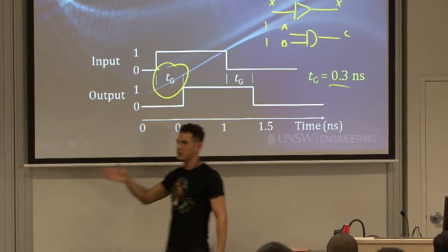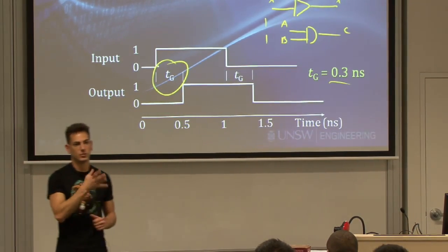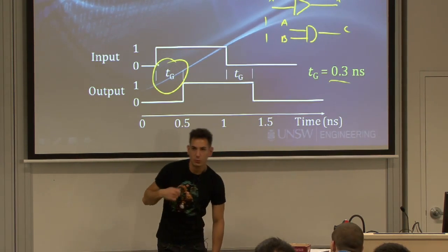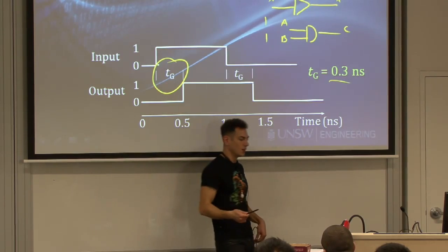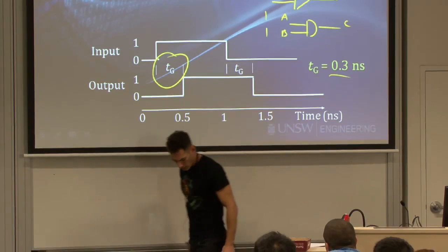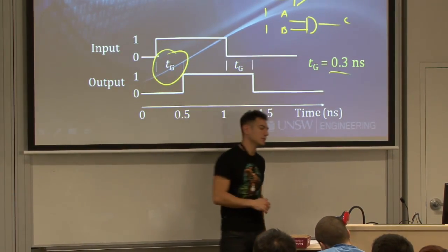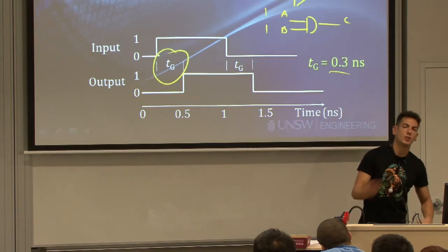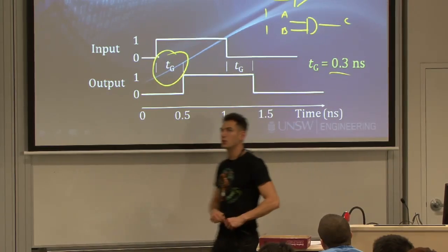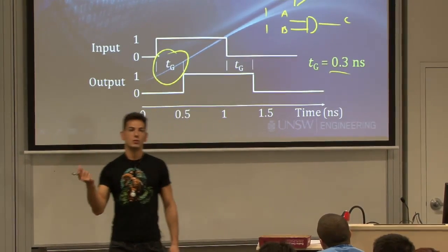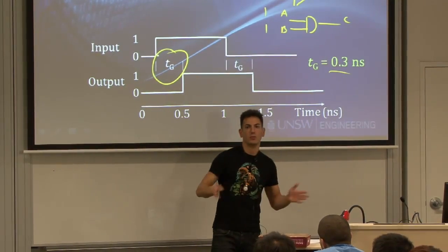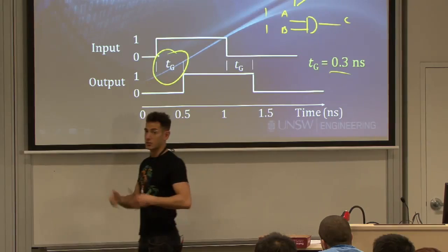When you do an operation on one side of the gate, it takes some time for the output to stabilize to the right value. If you clock the gate too quickly and you put new inputs into the gate too soon, you won't get the correct output from the previous operation. And this is what limits us with the clock speeds. There's always ongoing research about finding quicker technology. Obviously, the smaller you make your transistors as generations go, there's less path for the electrons to go through, and therefore we can actually speed up our computers.